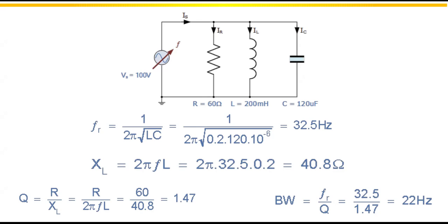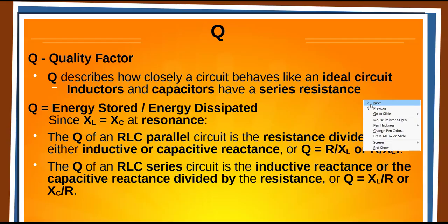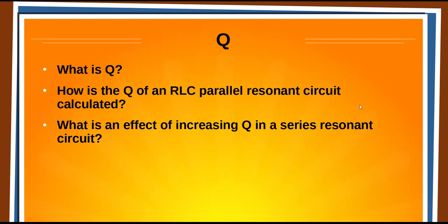I'm sorry, my question is how you're doing the circuit, not the math. So you see how your resistor, inductor, and capacitor are all in parallel. It's a truly parallel circuit. In your previous one, the resistor was not in parallel; it was feeding into the two parallel elements instead. Oh, it was? Yeah. You don't need to go back. That would make a huge difference, I think.